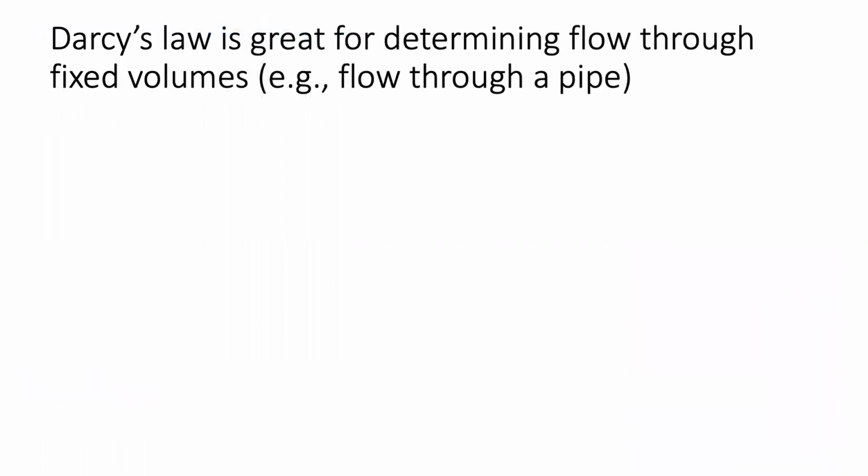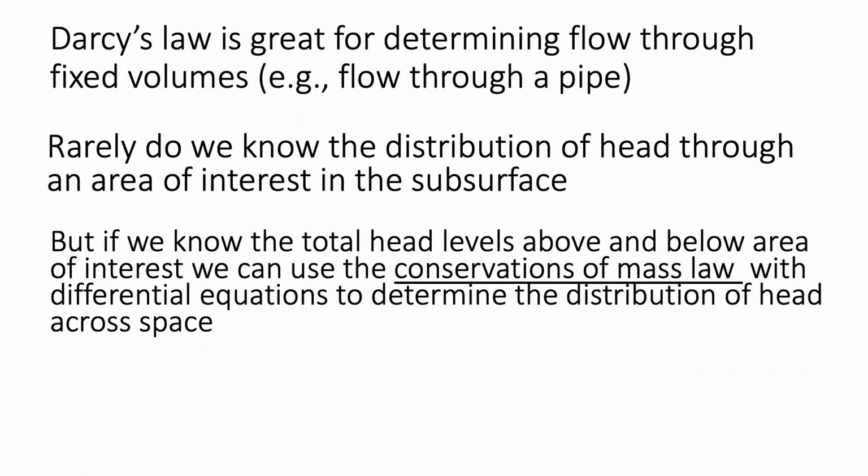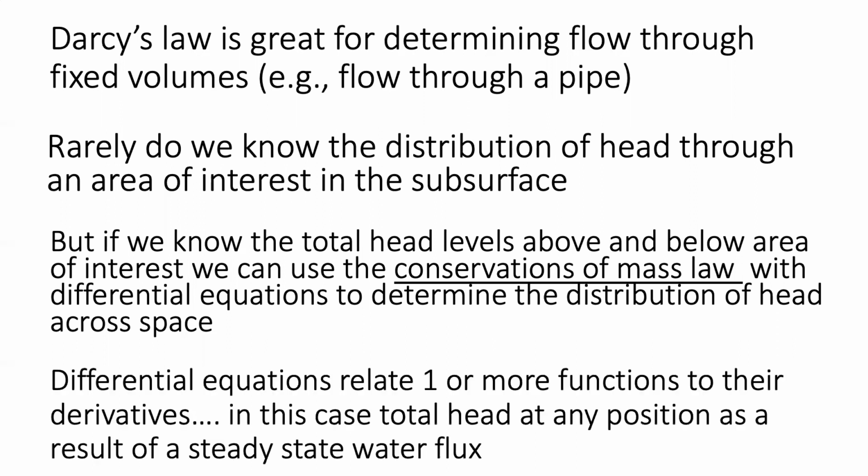So Darcy's law is great for determining flow through fixed volumes, right? Flow through a pipe. Rarely do we know the distribution of head, though, through an area of interest in the subsurface. We only have these wells that give us these peepholes into the subsurface. But if we know total head levels above and below an area of interest, so we have boundary conditions, we can use the conservation of mass law with differential equations to determine the distribution of head across space.